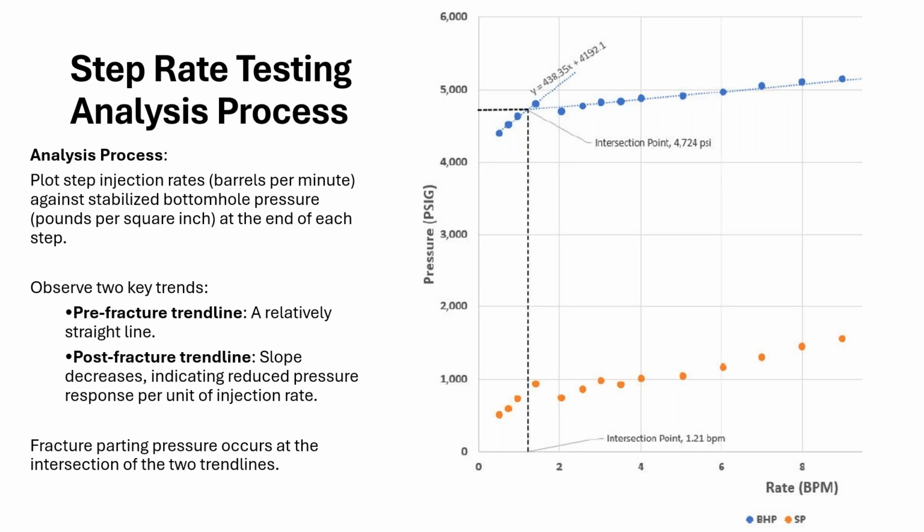So it does get difficult with some of your high volume injection wells where you're dealing with a 22 barrel per minute step. You're burning through a frac tank of fluid in 30 minutes, and it can be hard for your transfer company to keep up with that. So 30 minutes is the standard minimum. I've never seen anything less than that. And I would say with your higher rates, you just have to be prepared for water transfer to keep up. Note the volumes in your procedure and be prepared.